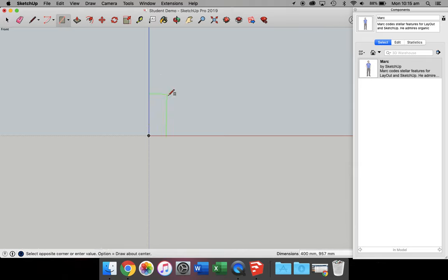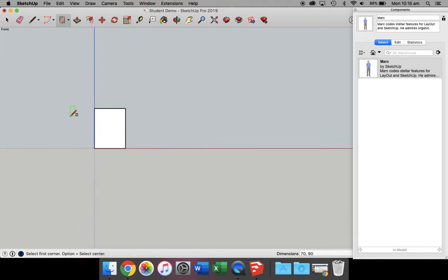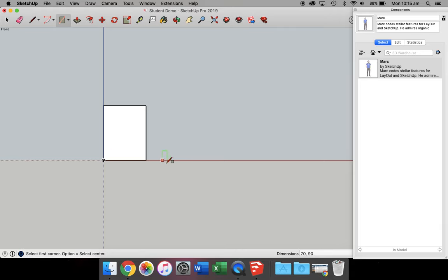Rectangular prism, and I'm now going to draw the cross section of my first piece. Now I'm going to start with the bearers. The bearers go at the base of the project here, and my bearers, when I'm reading the specification here, are 90 by 70 millimeters. Now what this means is they are actually 90 tall and 70 wide. Okay, and so we have a rectangular prism that looks a bit like that, 90 tall, 70 wide.